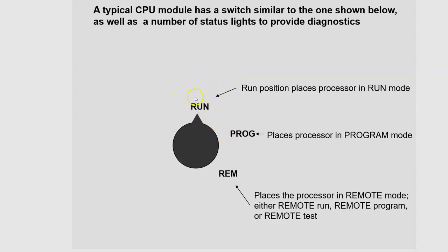When you're in run, you cannot edit, and when you're editing over here in program, you cannot run it. Hopefully you can see why that would be necessary, since this thing is actually going to be automating systems, and in some cases large and dangerous systems.